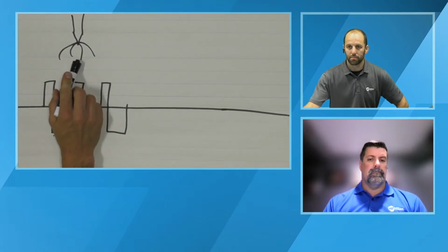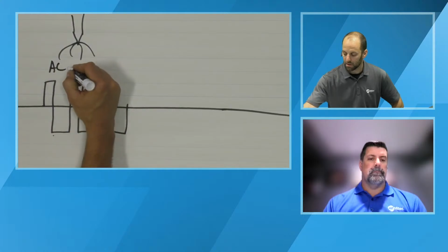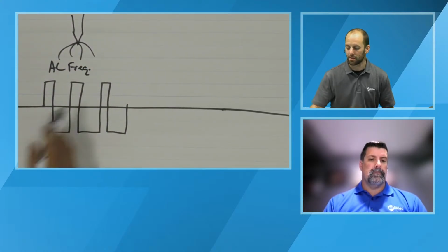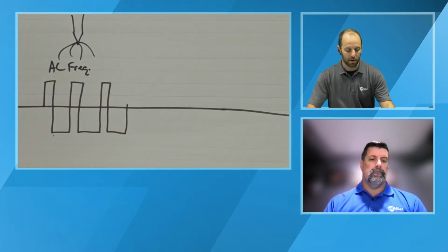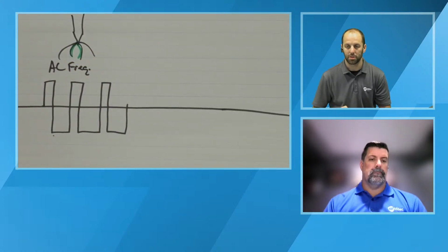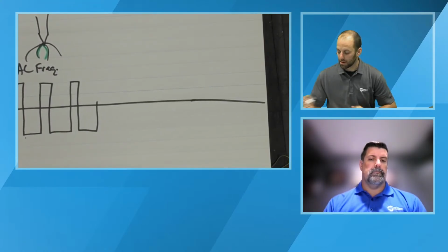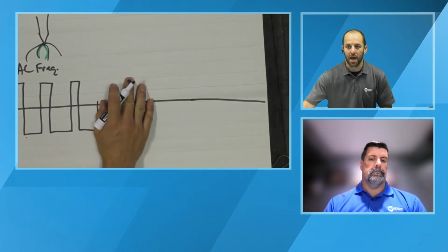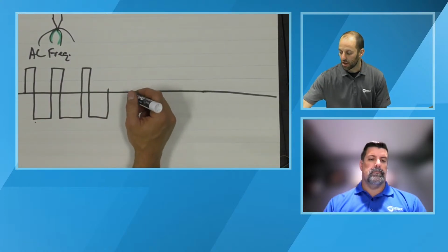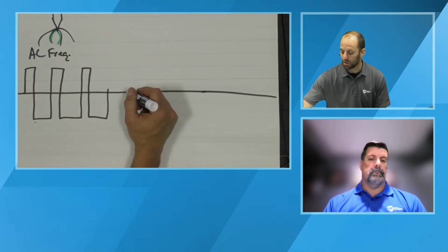And as we talked about last week, the AC frequency, making this happen at a faster rate, will focus our arc and really tighten it down to this shape here that we talked about. If you start throwing pulsing into the mix, especially if you have frequencies that match up with one another, what you may end up with is really goofy waveforms that are not predictable.